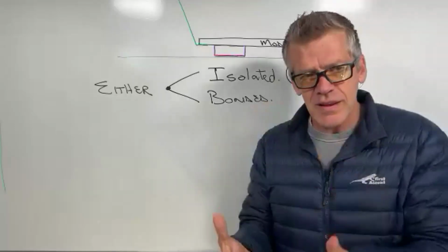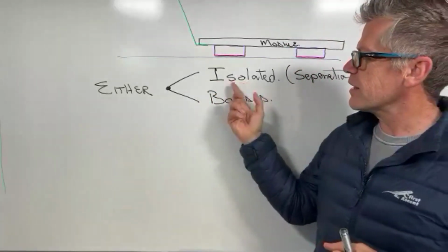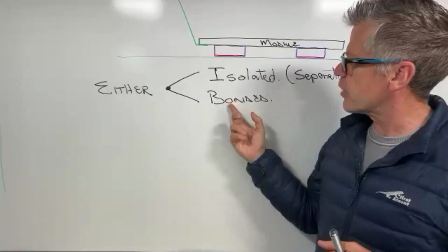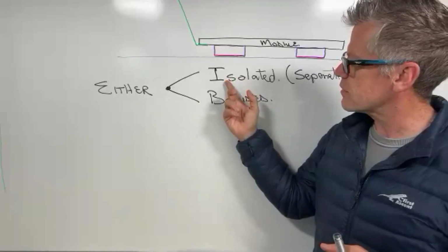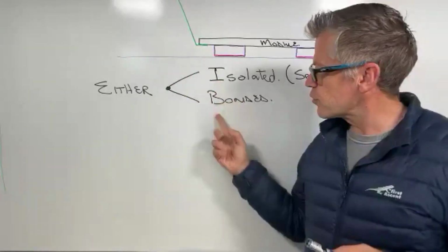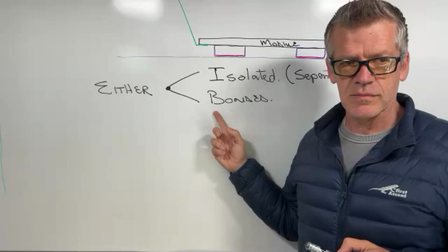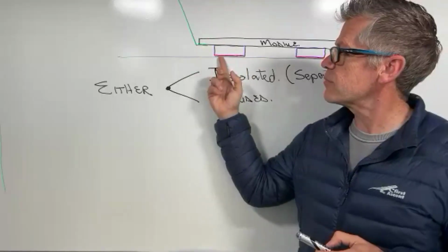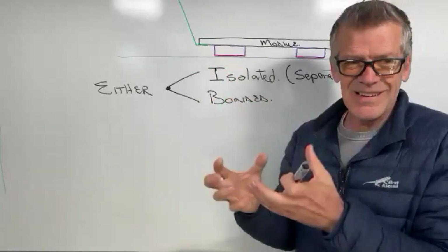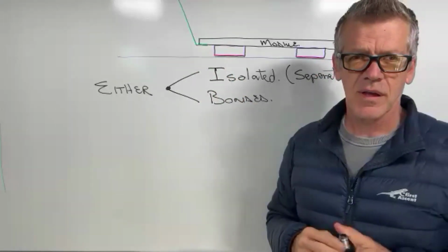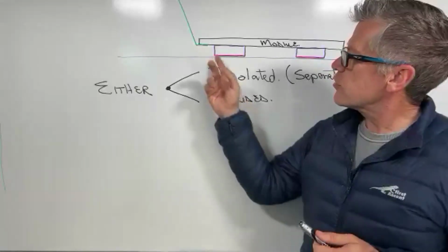So instead of planning the installation to be either isolated or bonded, the minute you've got a steel roof, you are forced to go with a bonded system, because your solar system is supposed to intrinsically become part of the same continuity of the metal. Am I right? Yeah, absolutely. Yes.